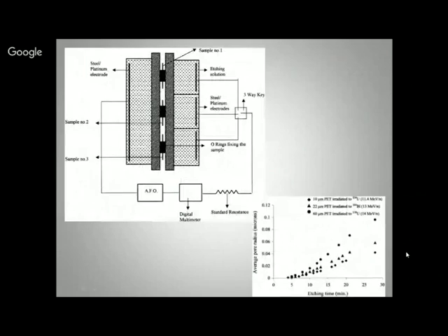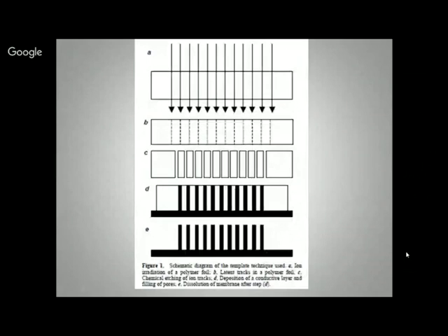So what we'll do, this is the technique that is known as template synthesis. First of all, we took a polymer and then we irradiated it with an ion beam. Ion beam means heavy charged particles. When they hit the polymer, they penetrate it, and when they penetrate the polymer, they create some reactive sites in the polymer, which you can easily etch using a chemical, and those sites get converted into pores.